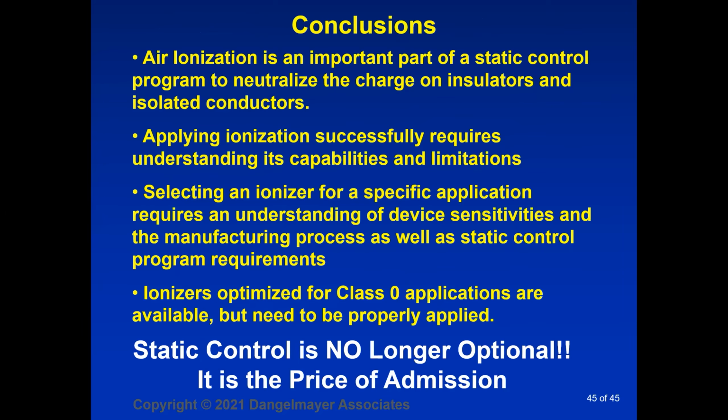So finally, in conclusion, air ionization is an important part of a static control program. It's there to neutralize the charge on the insulators and isolated conductors. It's not there for people. It's not there to replace any other part of the static control program. Applying ionization successfully requires an understanding of its capabilities and its limitations. What it can do, what it can't do. Is it working fast enough? Is it close enough? These are all things you'll need to determine.